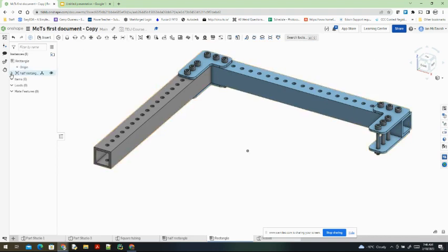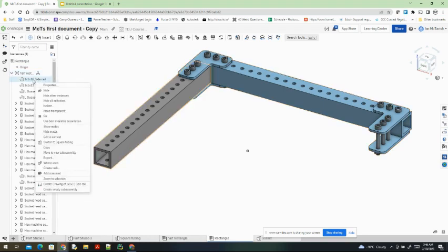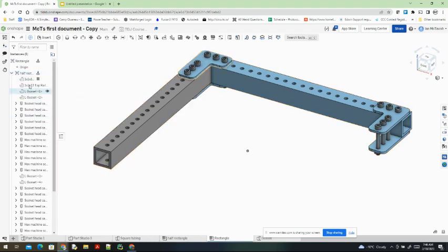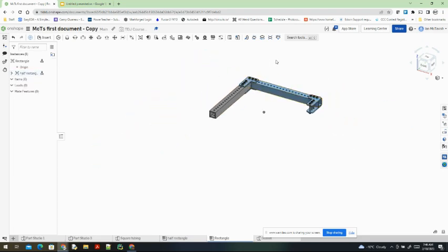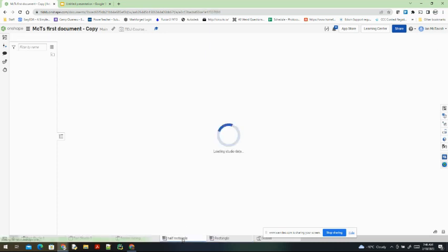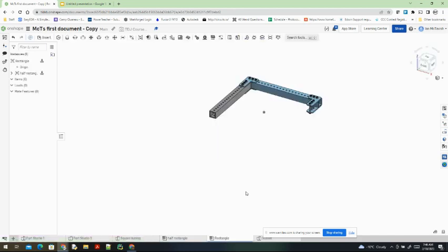So in my instances, I have the entire assembly in this little drop down. So I'm going to open up the drop down and I'm going to right click and fix that first part. And now because everything has fasten mates, nothing is dragged around. And if you notice one of your parts off to the side, it's probably in your half rectangle not fastened. Go back to the half rectangle, fasten it where it's supposed to be, and you'll see it in the right position then.